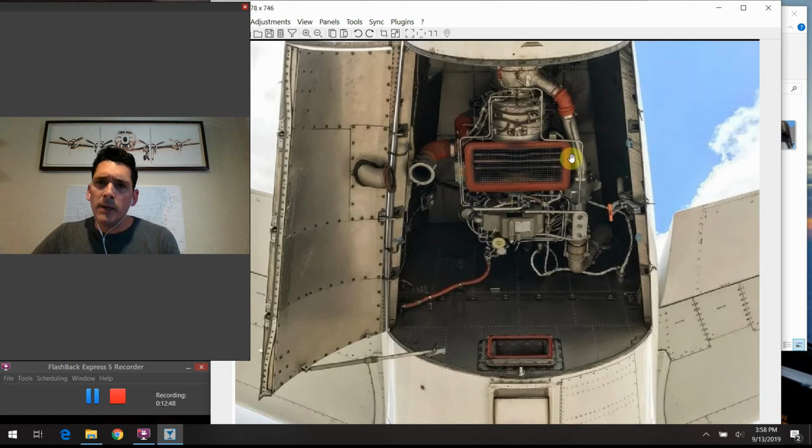So this is, like I said, the main air intake for the engine itself. This is an exhaust shroud piping here that actually goes out the backside of the airplane. You can see the outlet. It's kind of hard to tell from the way this photo is taken, but I think I have another one that shows it. But this is actually an oil cooling exhaust air line.